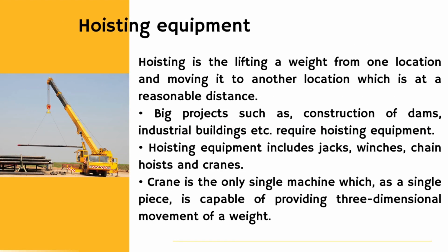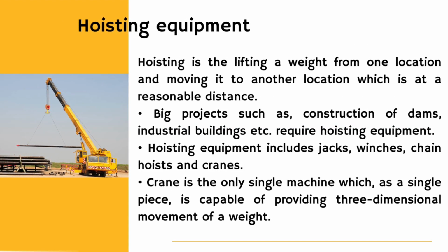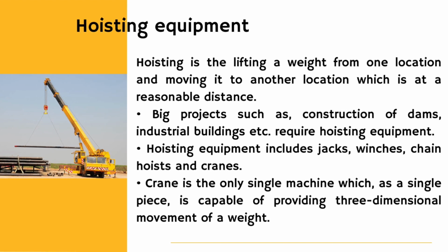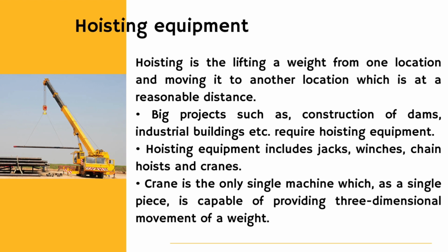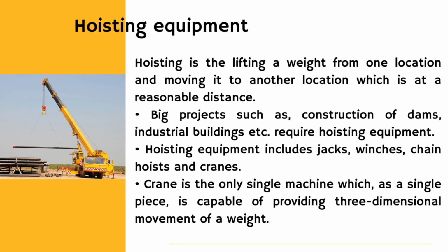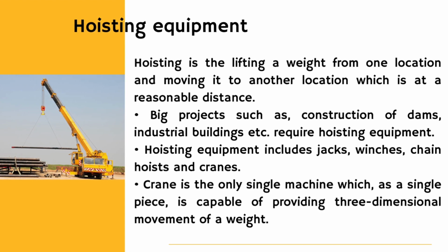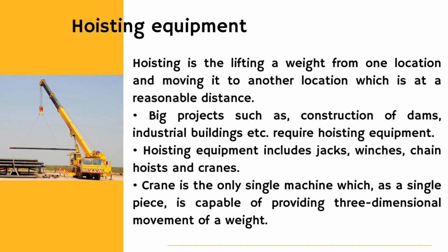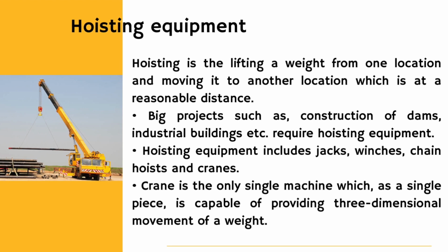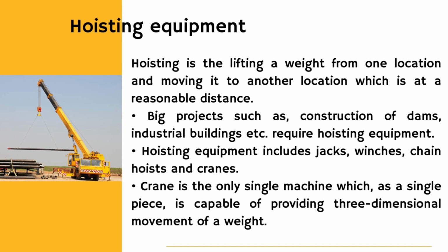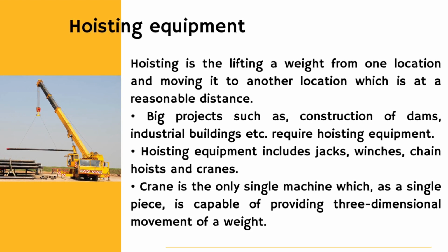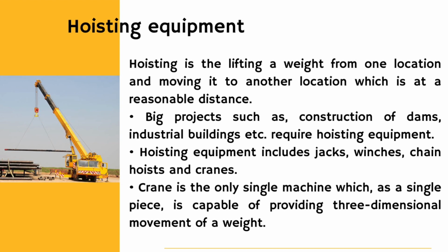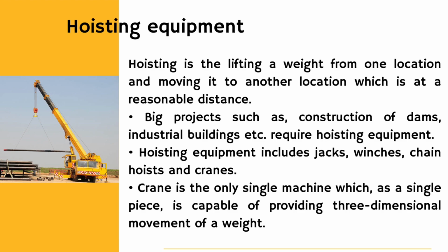Next is hoisting equipment. Hoisting is lifting a weight from one location and moving it to another location which is at a reasonable distance. Big projects such as construction of dams, industrial building, etc. require hoisting equipment. Hoisting equipment include jacks, winch, chain hoist, and cranes. Crane is the only single machine which as a single piece is capable of providing three-dimensional movement of a weight.